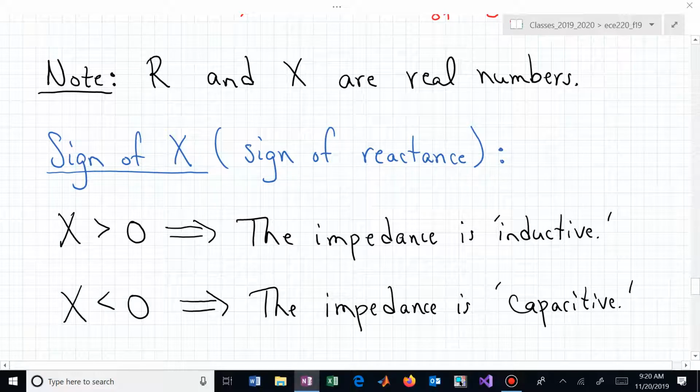When we were looking at the impedance of a capacitor, Z sub C was 1 over j omega C. The j in the denominator actually looks like a negative j if we bring it upstairs and put it in the numerator. There is now our negative value of X. We now have minus 1 over omega C for the reactance of a capacitor.